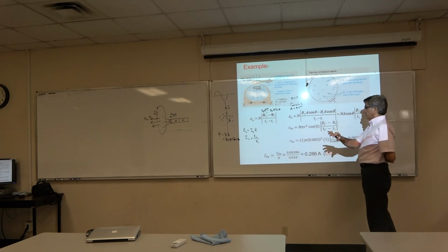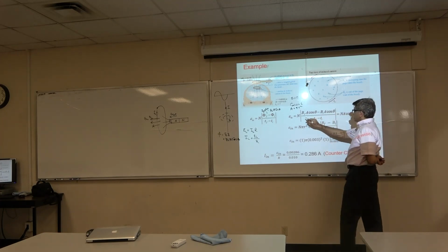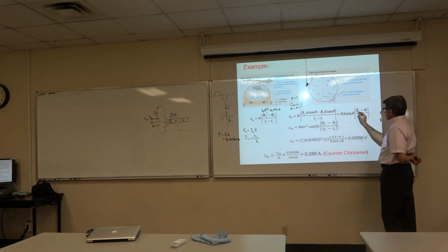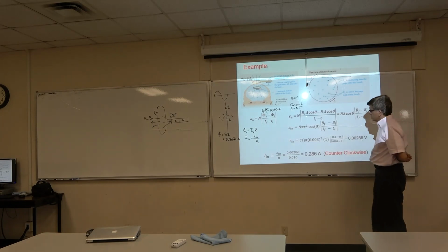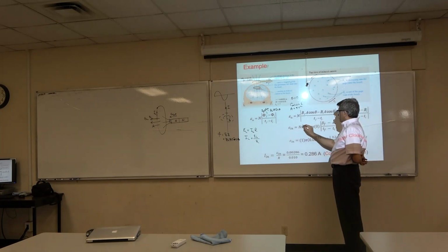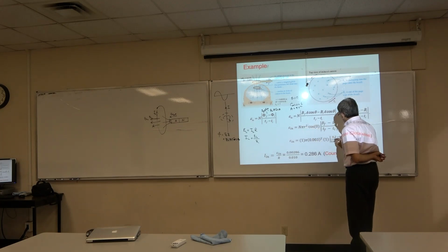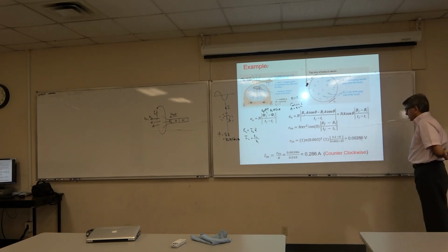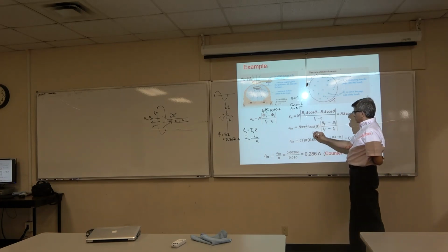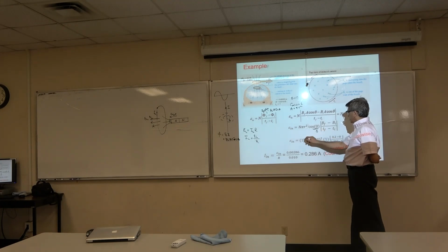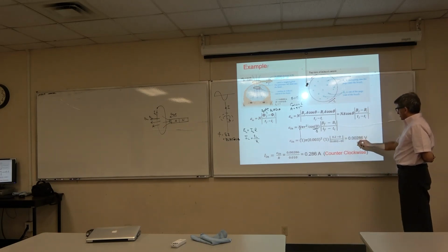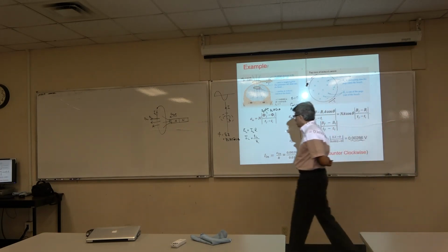What is changing is the magnetic field, right? So let's see, I sort this out: n number of turns, area remains the same, cosine theta remains the same. So the magnetic field is changing and the time is changing. Now n times pi r squared, which is the area, cosine of the angle 0. The magnetic field changes from 0 to 0.2 Tesla, and the time changes from initial 0 to 0.002 seconds. So I'll plug in everything over here. This is 1, n is 1. Then, plugging in the numbers, you get this much voltage. That is the induced EMF.